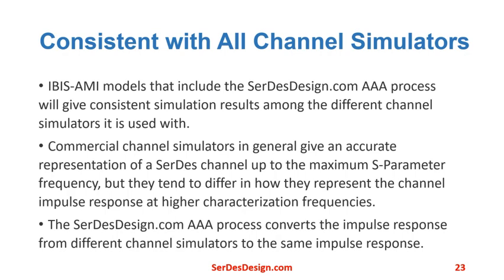Consistency with all channel simulators. IBIS-AMI models that include the SerDes anti-aliasing algorithm process will give consistent simulation results among the different channel simulators it is used with. Commercial channel simulators in general will give an accurate representation of a SerDes channel up to the maximum S-parameter frequency, but they tend to differ in how they represent the channel impulse response at higher characterization frequencies. The SerDes anti-aliasing algorithm process converts the impulse response from different channel simulators to the same impulse response.